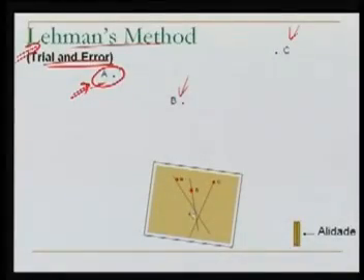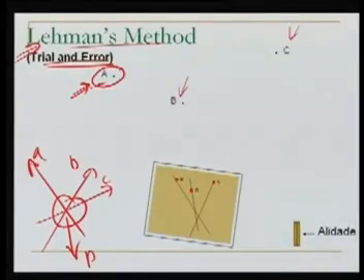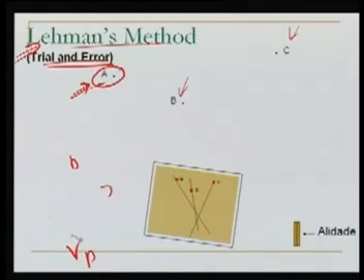Okay, that we can see here. Here is the triangle of error. This triangle we say is the triangle of error, which is formed here. If these three resectors to A, B and C meet at a single point, then there is no problem. The table is oriented, and this point is our small p, the point where we have occupied. But this is not the case here. In this case, they are forming a triangle of error.